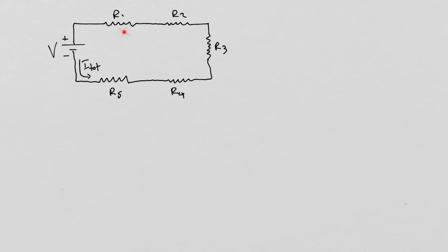If I replace those resistors with that one resistor that has a resistance equivalent to theirs, then the operation of the circuit will not change. We still will have the same amount of voltage supplied to the circuit by the power source, and still the same amount of total current in the circuit. So then I can replace this series circuit with a circuit that looks like that.